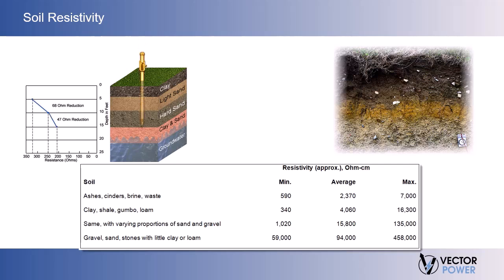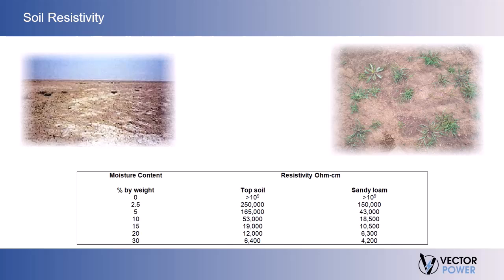Soil resistivity varies widely throughout the world and changes seasonally. It is determined largely by its content of electrolytes, which consists of moisture, minerals, and dissolved salts. Dry soil has high resistivity if it contains no soluble salts. In soil, conduction is largely electrolytic. Therefore, the amount of moisture and salt content radically affects its resistivity. Of course, the amount of water in the soil varies with the weather, time of year, nature of the subsoil, and depth of the permanent water table.